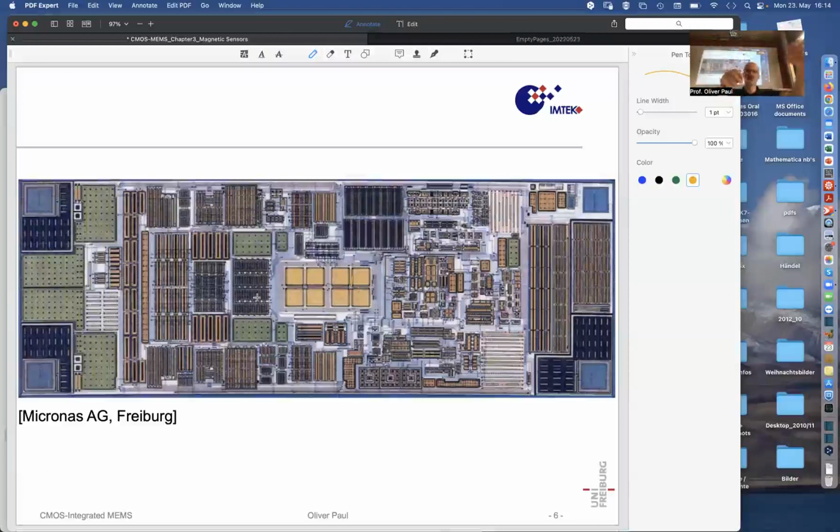And if those metal contacts are not at the same temperature, you experience a voltage difference due to the temperature difference at these contacts. That's a thermoelectric effect. And that needs to be compensated away for all possible directions of the thermal gradient. So having more than one, actually 2 is good, 4 is better, and maybe they have 8 here.